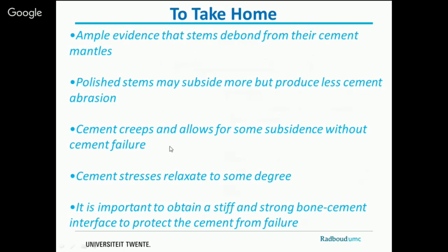These Exeter stems were one of the best stems, and these are the polished stems, so they do very well. Cement stresses relax to some degree, and it's important to obtain a stiff and strong bone cement interface. The surgeon has to pressurize the cement very well to get a stiff interface in order to protect the cement from failure, because otherwise we end up with a double number of cracks.